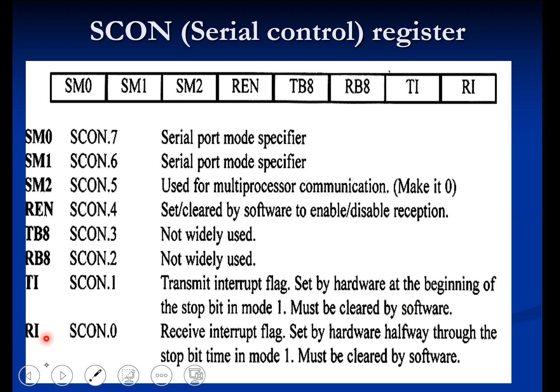RI, it is known as the receive interrupt flag. The receive interrupt flag is set by hardware to indicate the end of reception. End of reception means the data has finished there. It has to be cleared by the software itself.